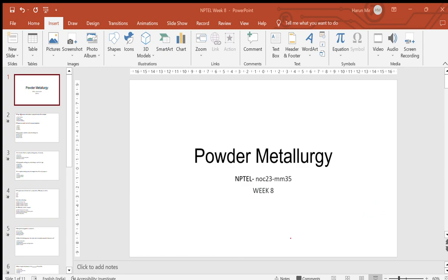What we require is very low viscosity, so that we have good flowability, and the powder flows throughout the mold. So you can say low viscosity is one parameter. Now what can you say about the pressure, high pressure or low pressure, among the parameters needed for successful molding? Out of the viscosity, we know that low viscosity is the correct option. For pressure, what is the correct option?